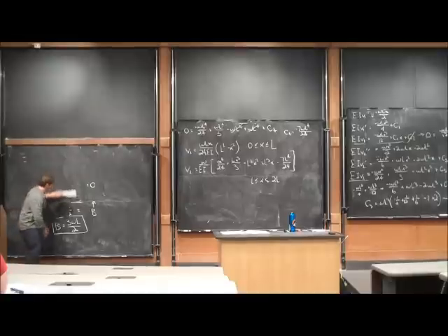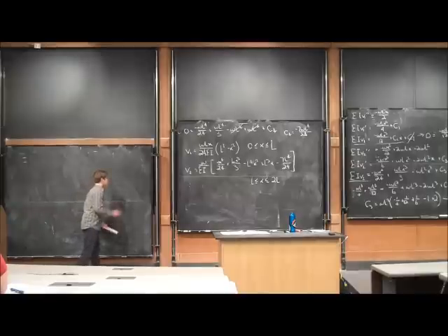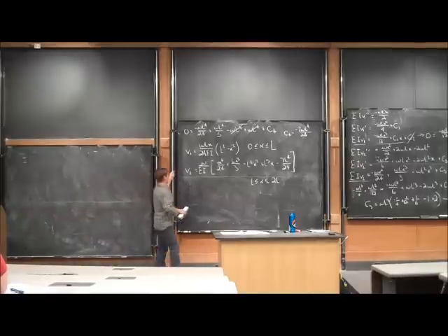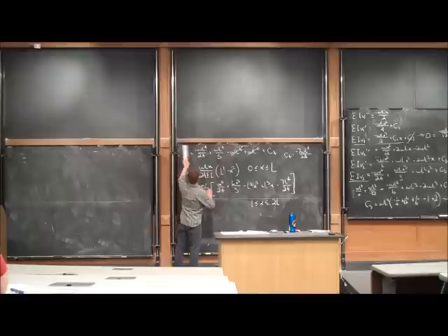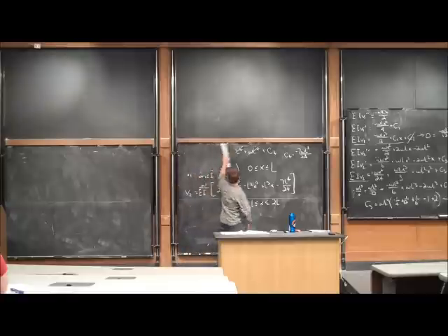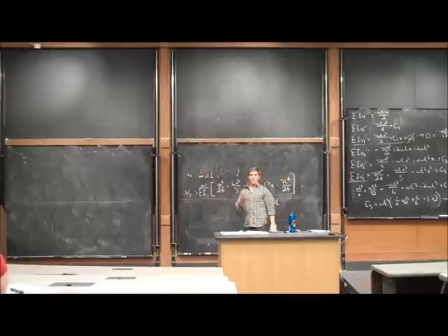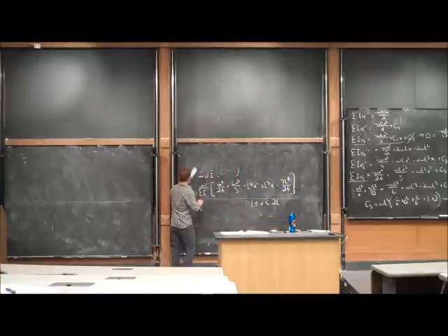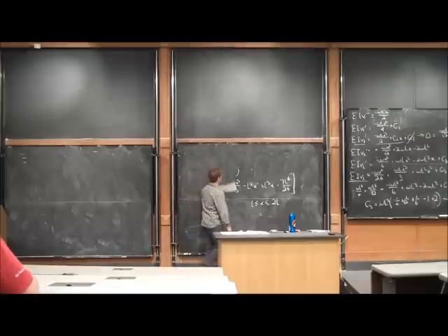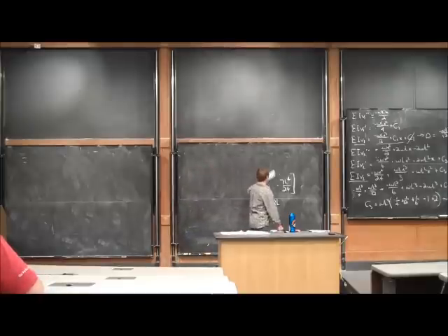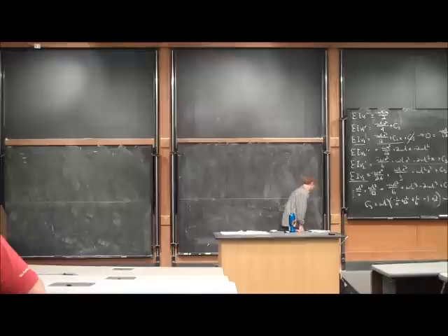Because we're going to take what we just learned, that we can integrate the moment equation twice to get the deflection. We can expand upon that and recall from what we saw doing moment and shear diagrams, and we can actually integrate the loading equation on a beam 4 times to get the deflection at every point in the beam. And while not always practical, it's something I guess we felt was important to include in the course.